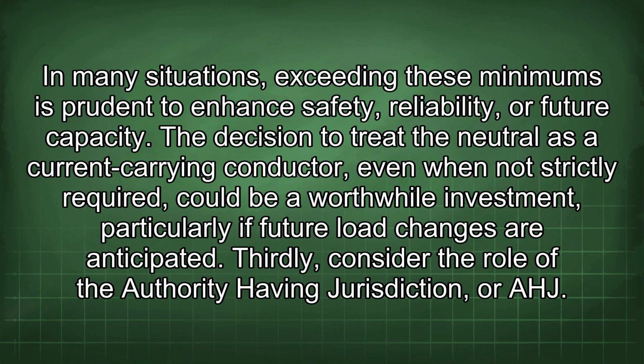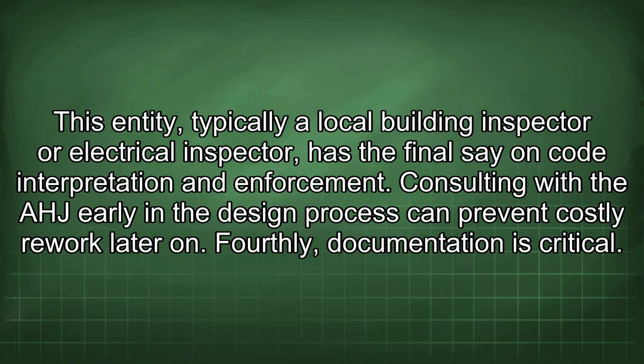Thirdly, consider the role of the authority having jurisdiction, or AHJ. This entity, typically a local building inspector or electrical inspector, has the final say on code interpretation and enforcement. Consulting with the AHJ early in the design process can prevent costly rework later on.